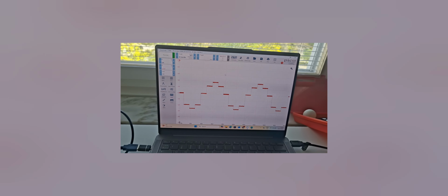which, as we can see, is centered at around 0 and has an amplitude of roughly 2.5 volts downwards and 2 volts upwards. The reason it's not symmetrical is because, again, we only have 3 bits of information to use, which means it's not enough to create a perfectly symmetric wave.